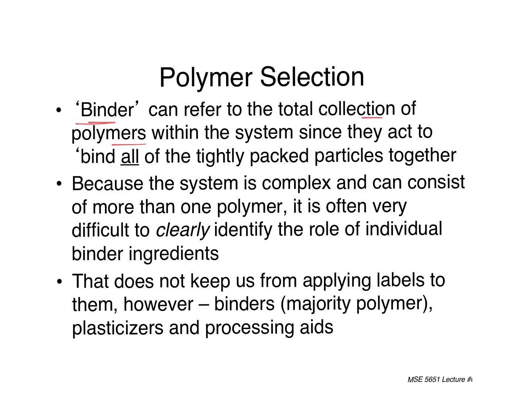We talk about binders being the polymer that occupies the space between the particles, and after everything's formed into, for example, this total knee, this is what helps hold it together. It's important because as you heat it up to remove the binder, that can be a problem. If it doesn't keep holding the part together, gravity can cause it to slump, then that total knee will change shape and you just pitch it, because it's not worth machining back to its original shape.